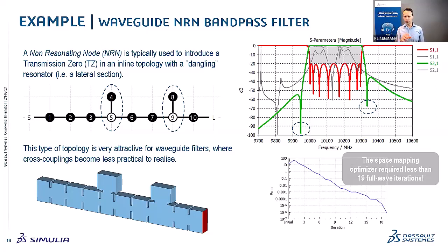I think what is important here also, from a practical aspect, is that you have specific susceptance values that you need to implement. So for example, talking about a positive susceptance, which typically realizes the low side transmission zero, you need to hit the right length of the wavelength between the first and the second order mode.